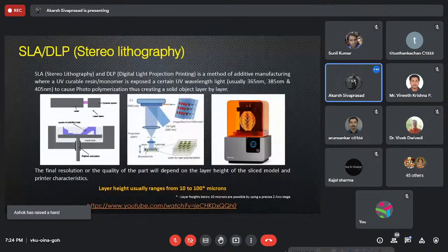And so talking about the pros, this technology can print anywhere down to 5 microns in Z to almost 100. So that's a huge range. And I think DLP SLA is one of the most widely used technologies in the research and the precision field, because you can print your knife edge with this, because your mirror size is close to 5.4 microns, which is more than enough to make your knife edge. It'll still not be a knife edge, but it's a much closer representation to what FDM can do.